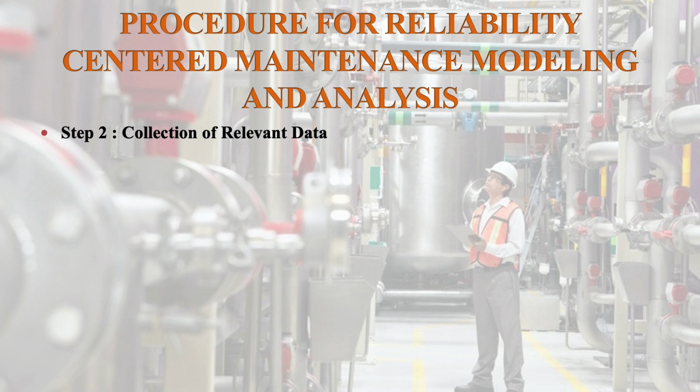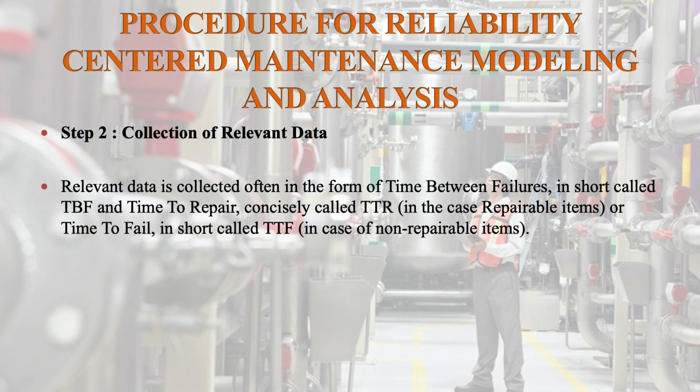Step 2. Collection of relevant data. Relevant data is often collected in the form of time between failures, in short called TBF, and time to repair, concisely called TTR, in the case of repairable items, or time to fail, in short called TTF, in the case of non-repairable items.